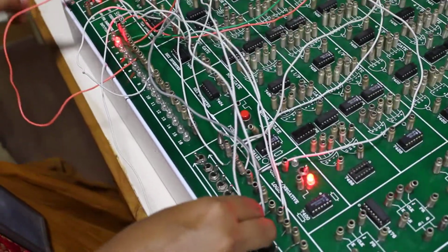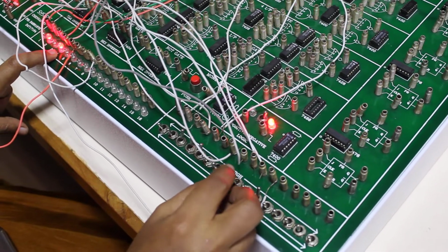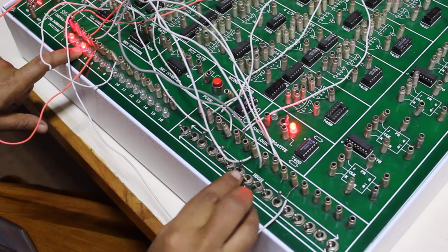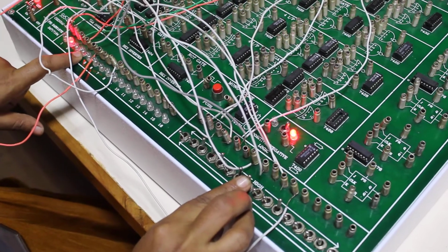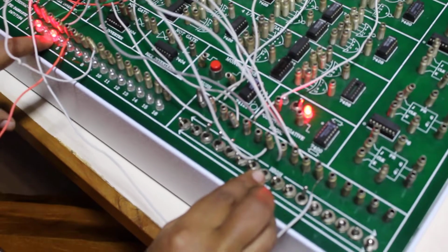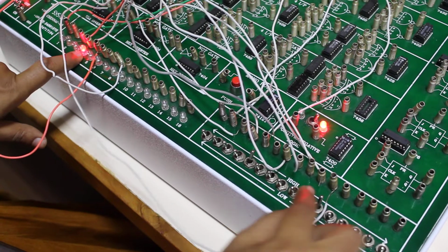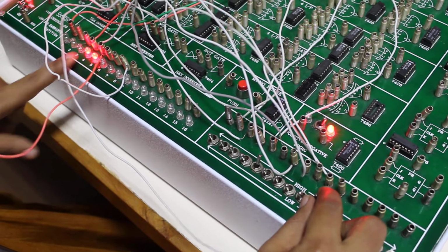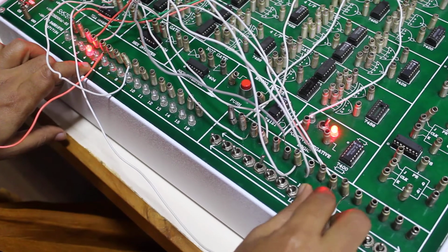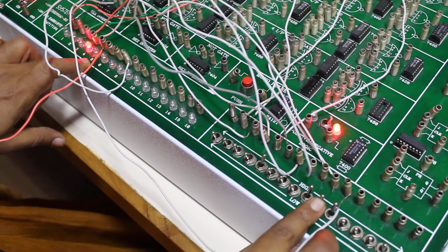So let us take the conditions. When either of the inputs is 0, you have the output as 1, 0 1 also 1, 1 0 also 1. When both the inputs are 1, your output is 0. Once again, I'll tell you the connections. I'll turn off the other lamps. When both the values are 0, the output is 1. For the 0 1 condition, it is 1. Just check LED 5 alone. For the 1 0 condition also it is 1. For the 1 1 condition alone, this LED goes to 0.